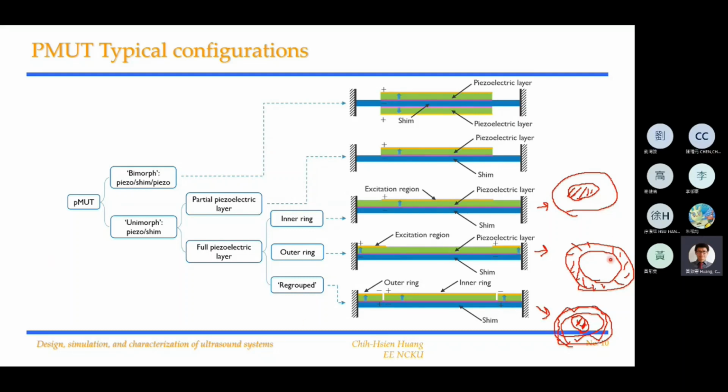Typically, the shape of the electrodes will also define the resonant frequency you are going to drive, because the shape occupied by the electrode is based on the vibration mode you are looking for. If you are looking for the first mode vibration to be your resonant frequency, then you will put the electrode at the locations of highest movement in the first mode.